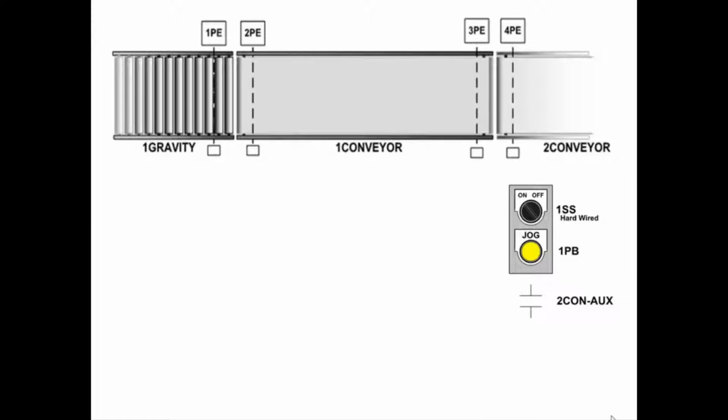Cartons are unloaded off of a truck and placed at the top of the gravity conveyor, and they roll to the lower end, coming to a rest against one conveyor's leading edge. In other words, they roll into photo I1 but not photo I2, so they come to rest against the unmoving leading edge of the second conveyor, one conveyor.